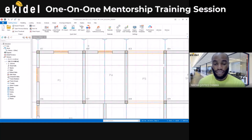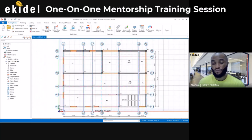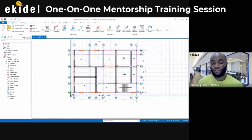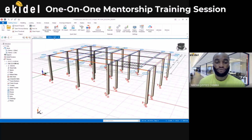Now, once you've done that, we are currently on the plan view. For us to navigate to the 3D view from our plan view, you come under your tree here, you can see View. Right click on View, you will see 3D physical model. You click on that. Then you can see this tab now showing here. Now you have plan view and then you have 3D.